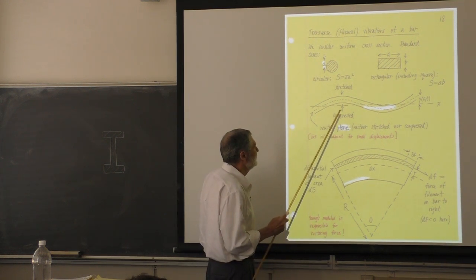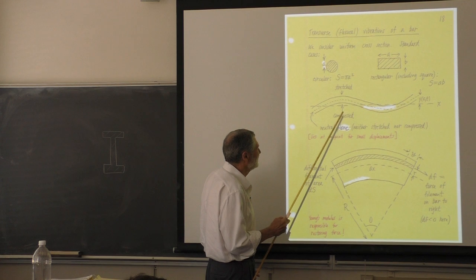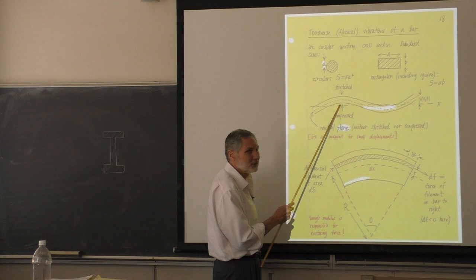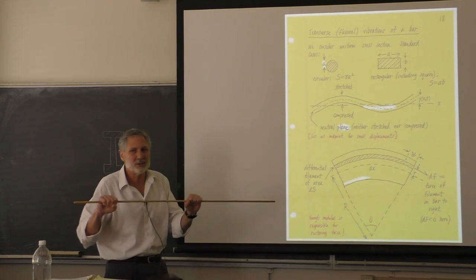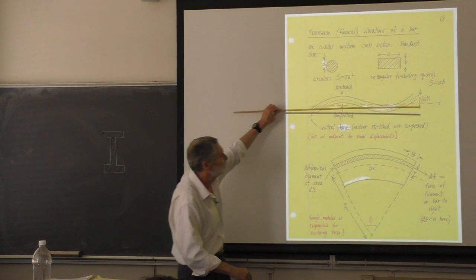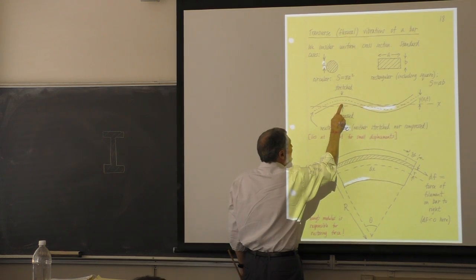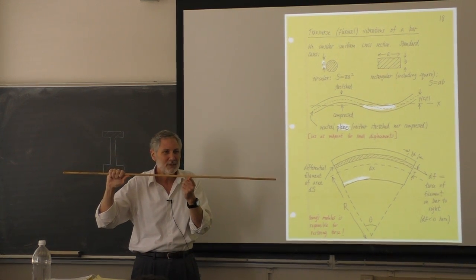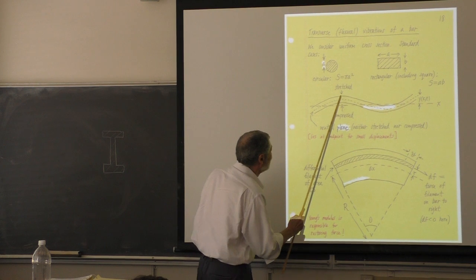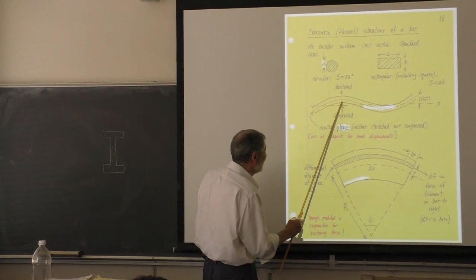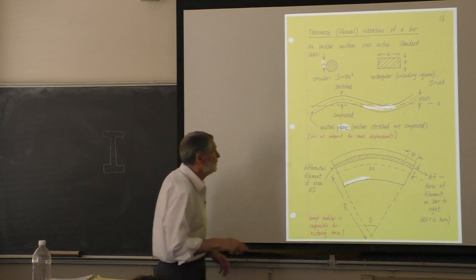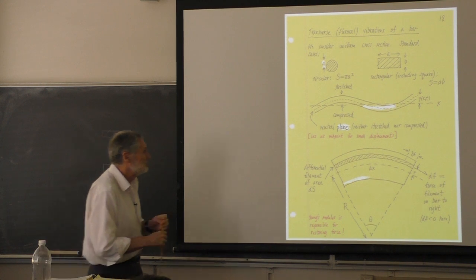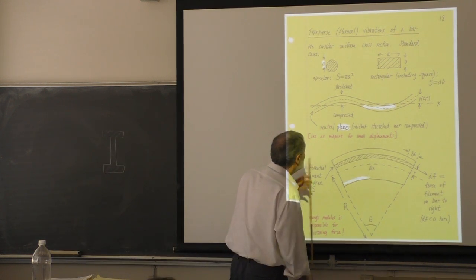So immediately here you see what's peculiar about these waves: up here the material has been stretched compared to equilibrium, where it's uncompressed or unextended, right? In equilibrium right here. Here it's stretched. What's happened here? When I go like this, what happens down here? It's compressed. So at the same x location, we have stretching, extension here and compression here. Somewhere in between there's going to be what's called the neutral plane. This is where it's neither stretched nor compressed. It's at its equilibrium value.